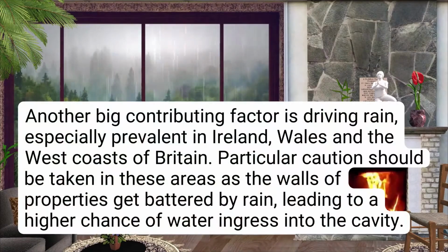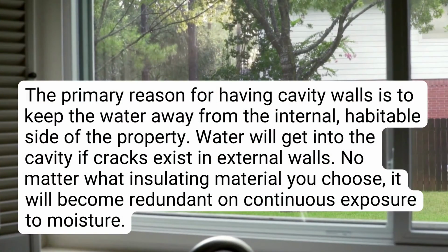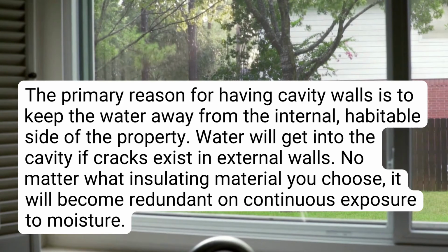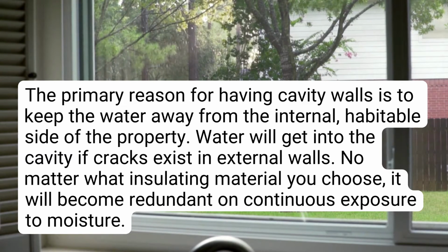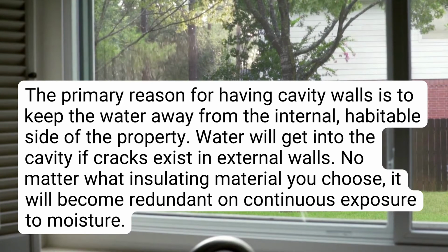Another big contributing factor is driving rain, especially prevalent in Ireland, Wales, and the west coasts of Britain. Particular caution should be taken in these areas as the walls of properties get battered by rain, leading to a higher chance of water ingress into the cavity. The primary reason for having cavity walls is to keep the water away from the internal, habitable side of the property. Water will get into the cavity if cracks exist in external walls.